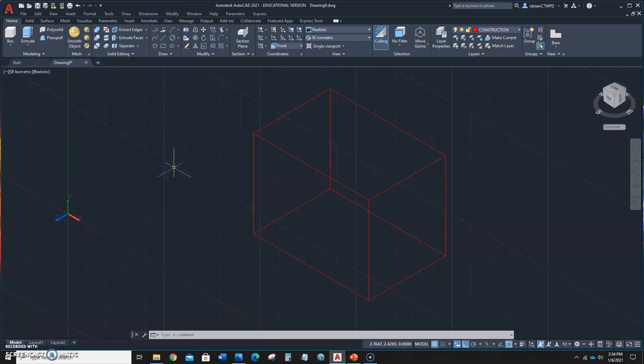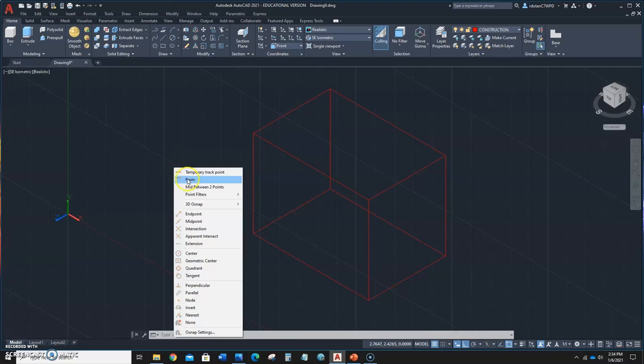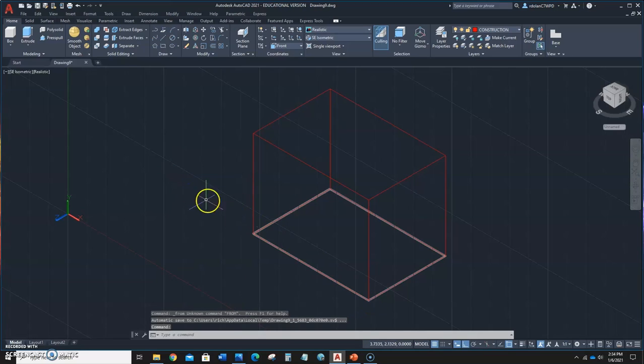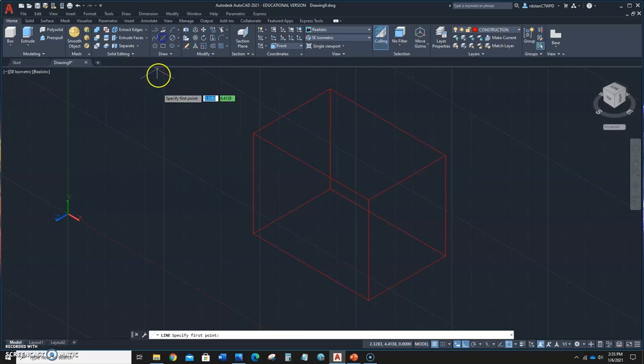And what I'm going to use is I'm going to pick a line, go from this endpoint right here, okay, and then at 0, comma 0.75, okay, which again made it from this point 0 in the X direction and 0.75 in the Y direction.